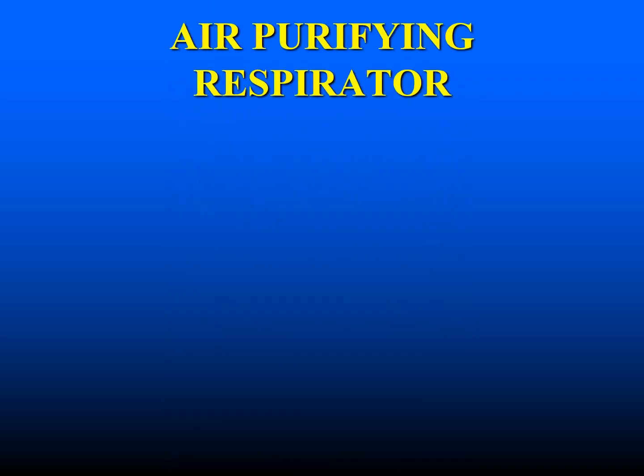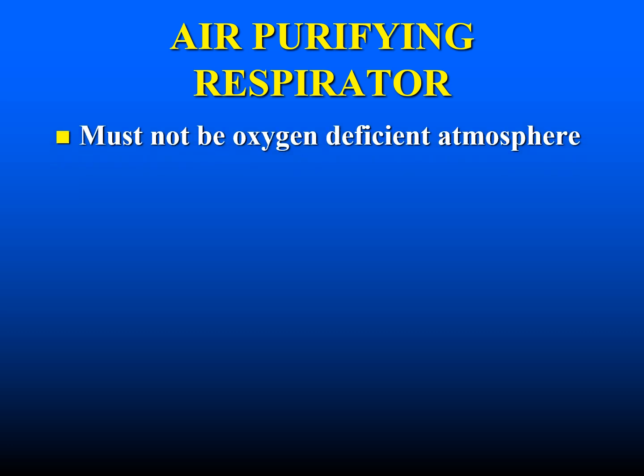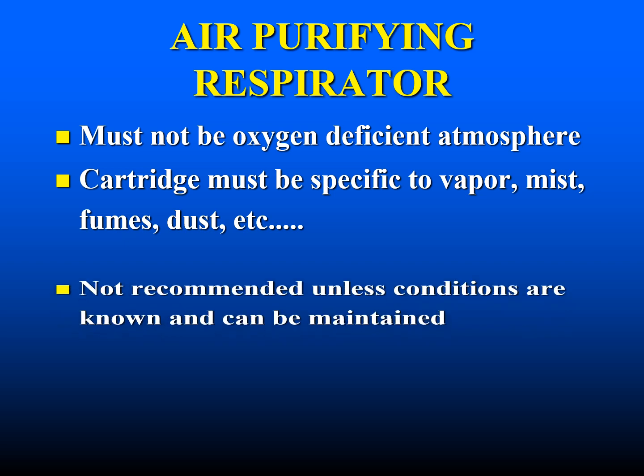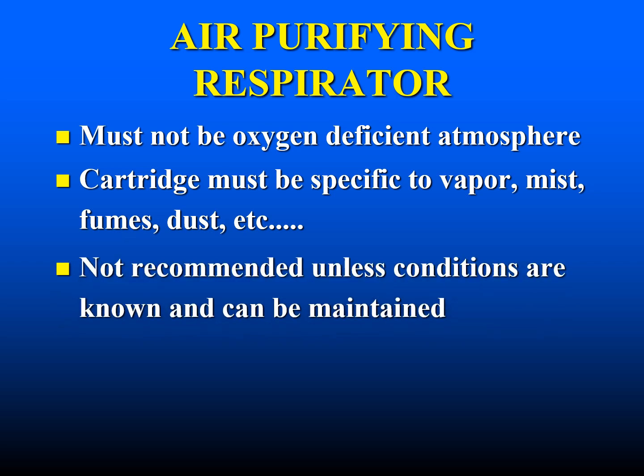Next, I want to talk about the air purifying respirator. We have to make sure that the space we're going to enter is not oxygen deficient. The cartridge must be specific to vapor, mist, fumes, dust, or etc. An air purifying respirator is not recommended unless conditions are known and can be maintained.